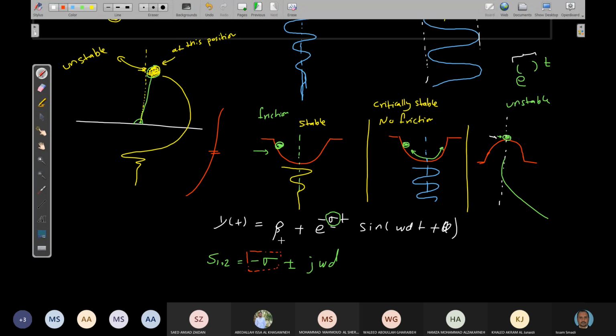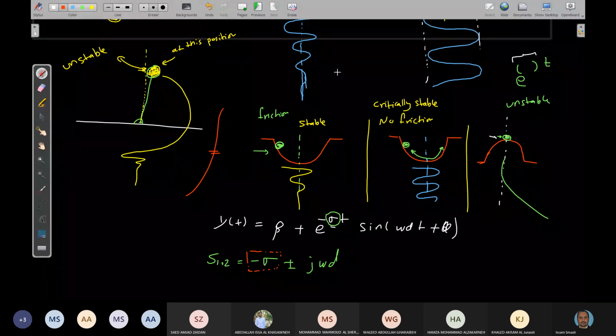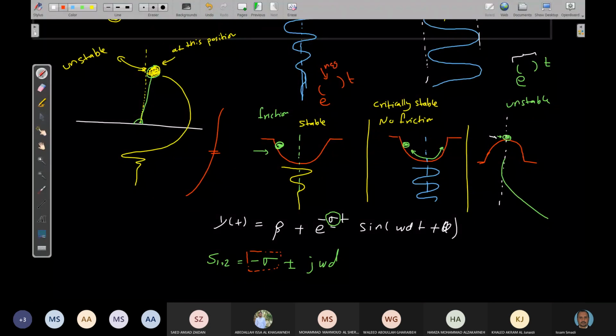And if the system is stable, then simply the dynamic must go to zero, and I will end up with y steady state. This means that if the system is stable, then the real part of the root must be negative. Why? Because I need the exponent in the exponential to be negative here, correct? Yes. Good.